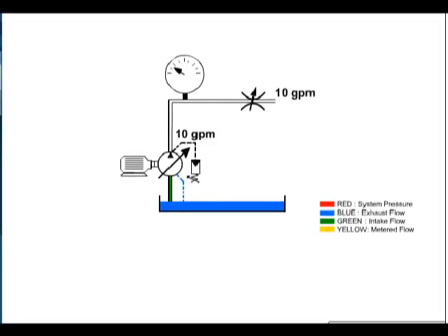When flow control is used in a pressure-compensated pump, fluid is not pushed over the relief valve. As pressure approaches the compensator setting of 1500 psi, the pump will begin to de-stroke, reducing output flow.